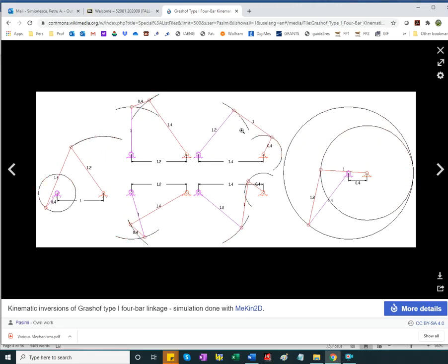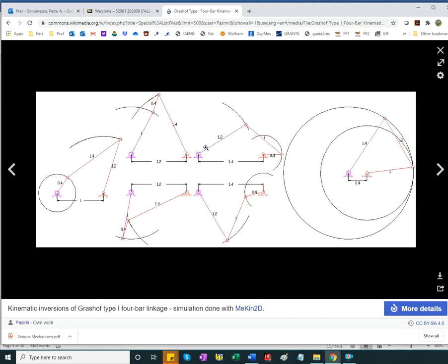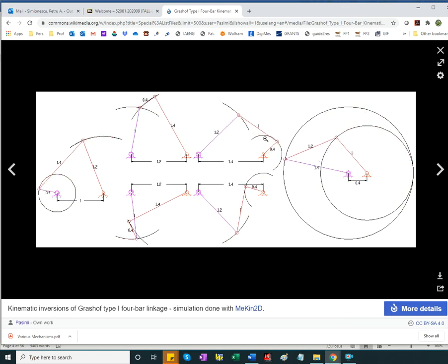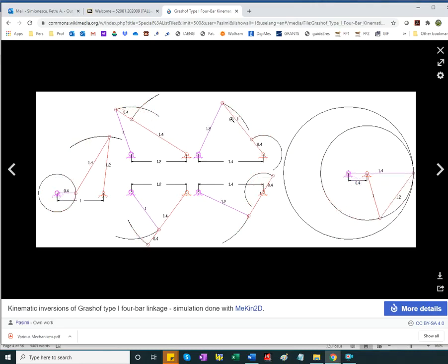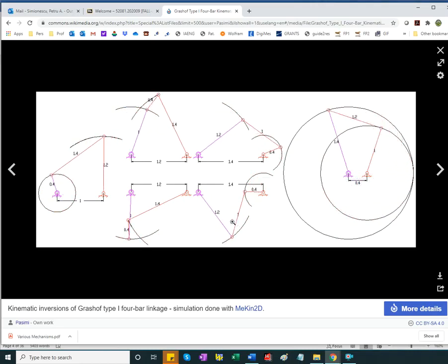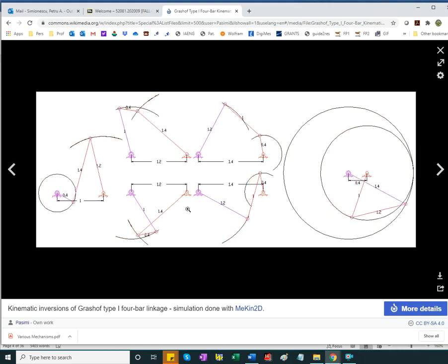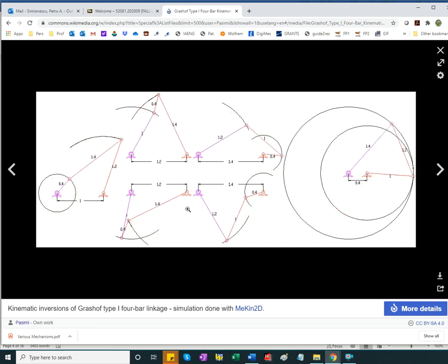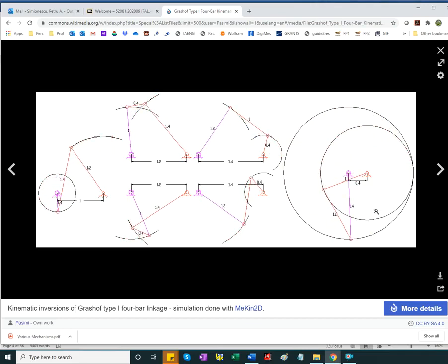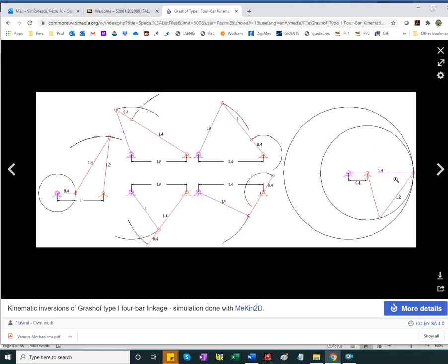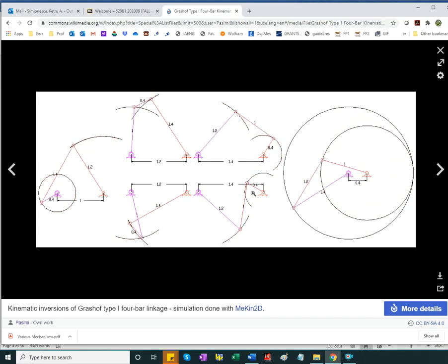I have the rocker case. The input is the 1.2 length link, and you can observe the limit positions. They are in line. In the mirror case, you'll see it has a meaning. It's a matter of having a minus or plus in front of some square root, but that will be for chapter 3. And this is the drag link mechanism. All 3 links perform full rotation. The coupler including, you can see if you watch it, it too performs full rotation.